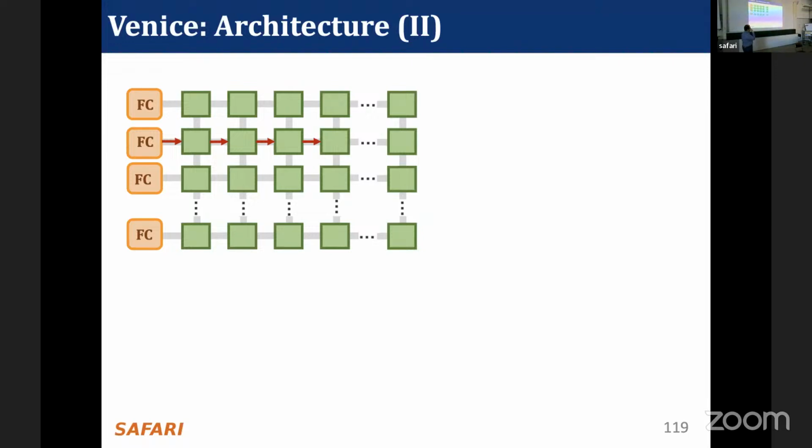The router chip that we have here is quite simple, as I said, because first of all, we don't use big buffers. Our buffers are quite small here. They are just large enough for a scout packet, and a scout packet is 16 bits, as far as I remember. So our packets are quite small, our buffers are small.